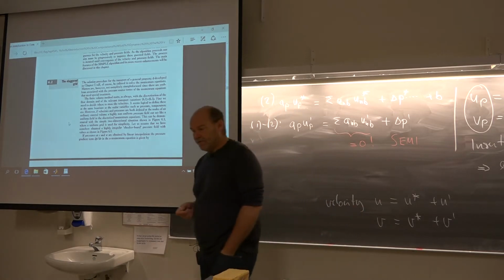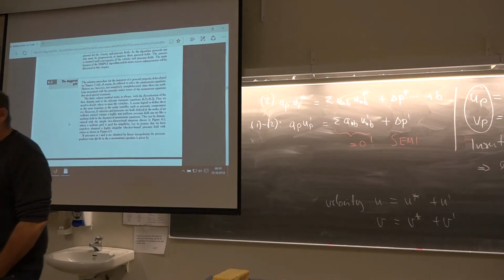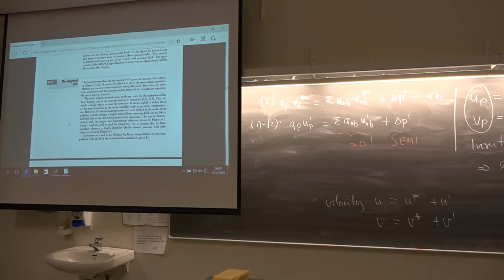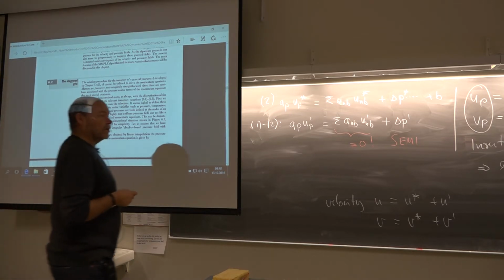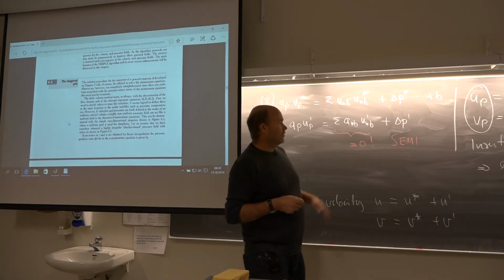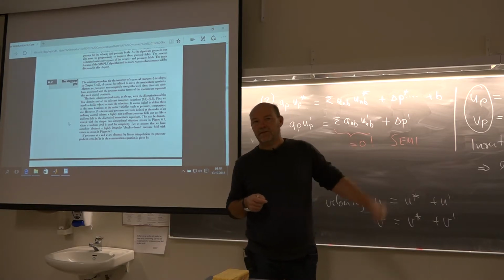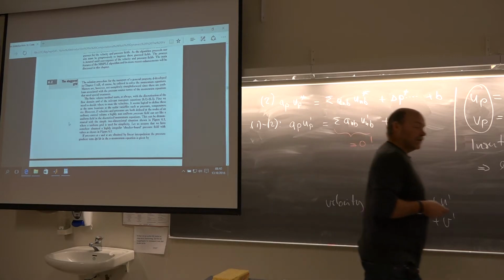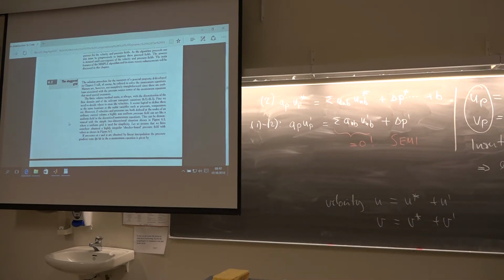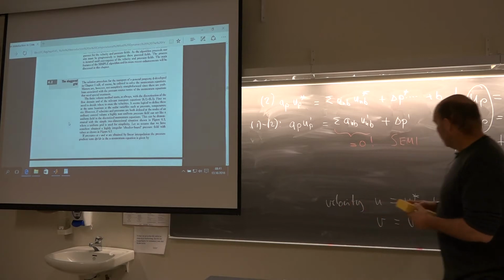And yes, it is very, very similar to the time-splitting algorithm, the projection method that we used in Sola. And if you do this with a uniform mesh, you will see that it is actually identical. It's exactly the same as the projection method. And yes, we also there used the continuity equation, if you can recall. So this will now be the standard SIMPLE algorithm.